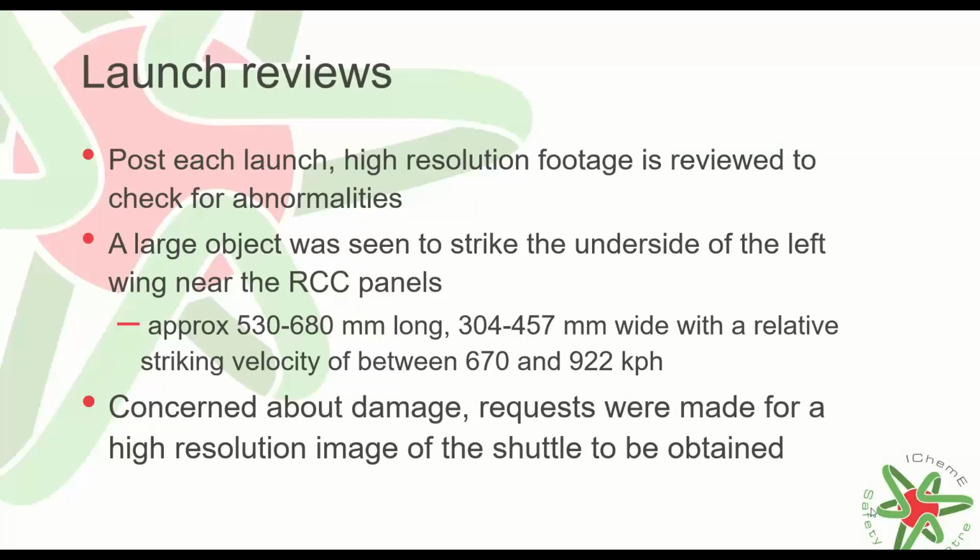So it was interesting in this whole process that they do have a launch review process. After every launch is undertaken, a group of engineers and specialists review all of the data to see if there's any abnormalities. And they detected that there had been a substantial debris strike, and it occurred somewhere near the reinforced carbon-carbon panels, and that it was quite a large piece of foam and was travelling at quite a substantial speed when it actually hit.